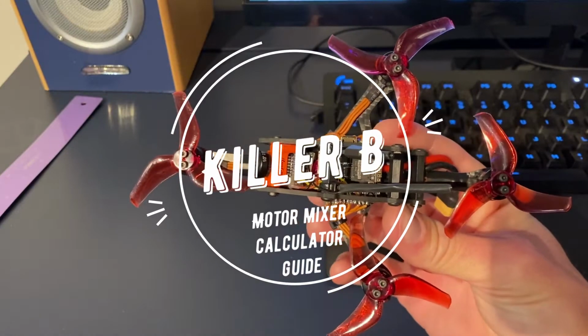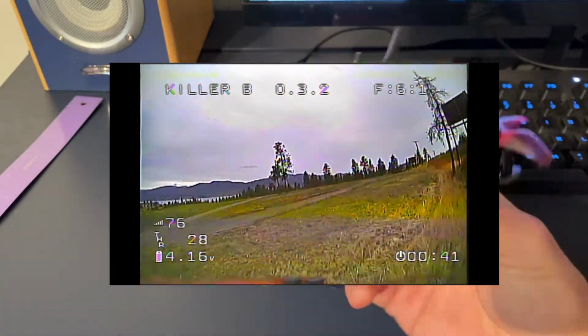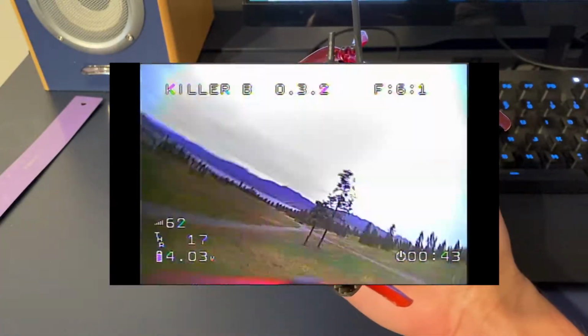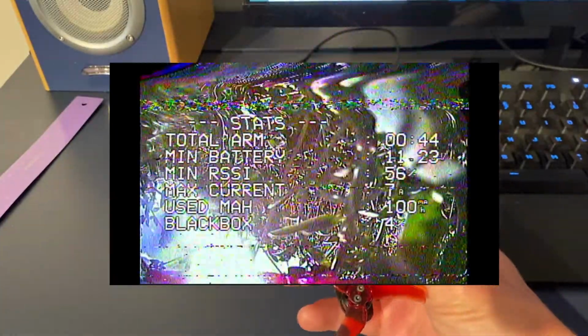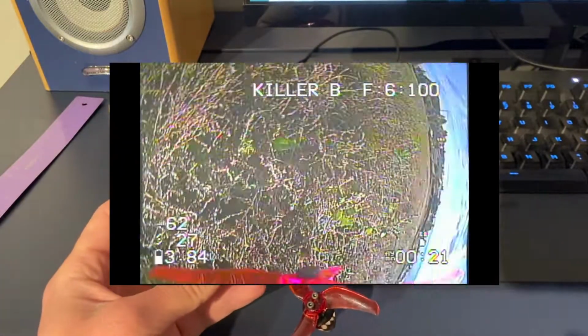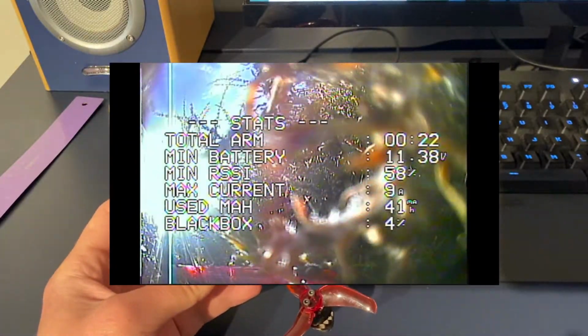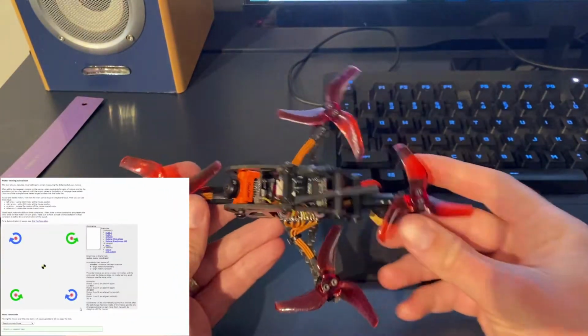In setting up my Quad Plus frame, I was dealing with some unusual issues on the roll axis. My drone would go into a death spiral, and I wasn't sure why. It was suggested to me that it could be things related to PIDs or to ESC desync, but I didn't think that was the case since everything seemed healthy.